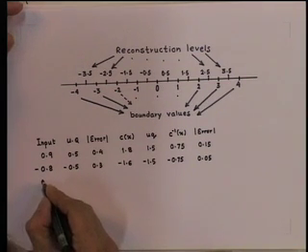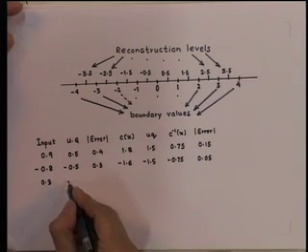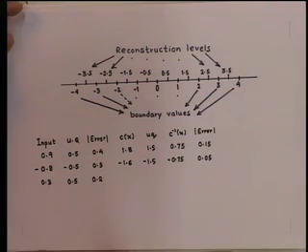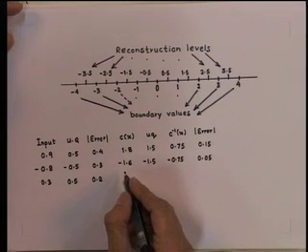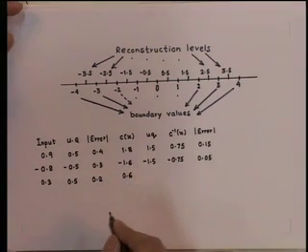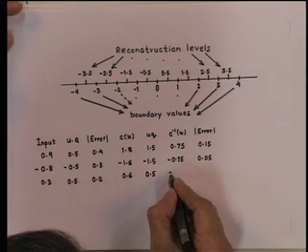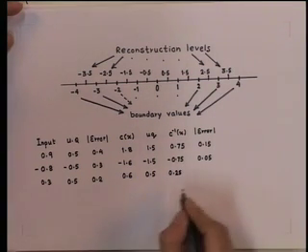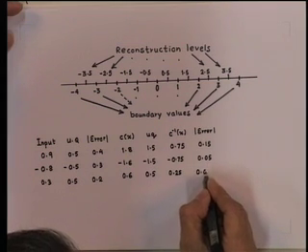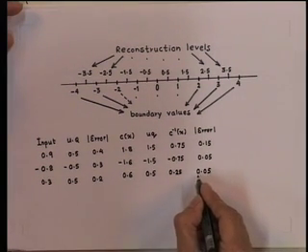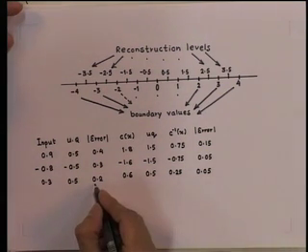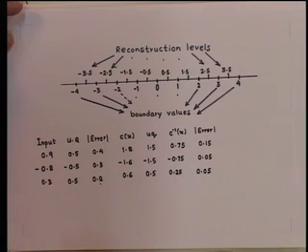Similarly, we could extend this to 0.3, this would give 0.5, the error is 0.2, and when we pass through the compressor it will give 0.6, which will be quantized to 0.5, pass through the expander will give 0.25. So, the error is 0.05. Again the error here with the compander is less than without the compander.